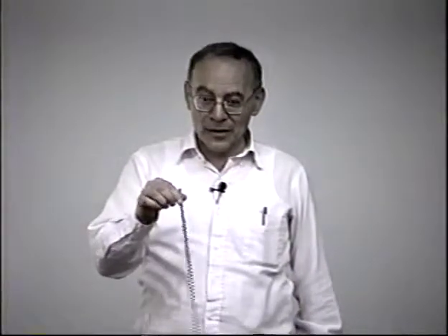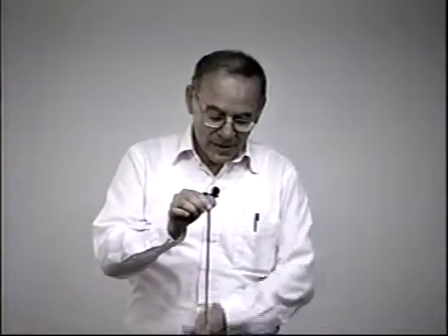This is called the bang-bang control. If the control can be between 0 and K, it chooses to be either at 0 or at K. If you want to bring a pendulum to equilibrium as fast as possible, and you are only allowed a certain amount of force at each time, like this or like this, and the force is between 0 and 1, you always hit it with either 0 or 1. No, between -1 and +1, both ways. So either -1 or +1 at different times, and that's how you bring it as fast as possible to equilibrium. That's the bang-bang principle.